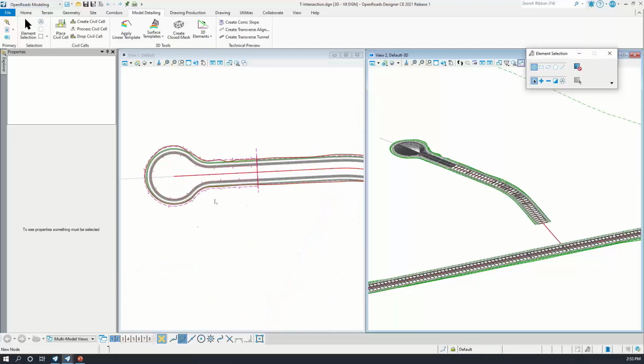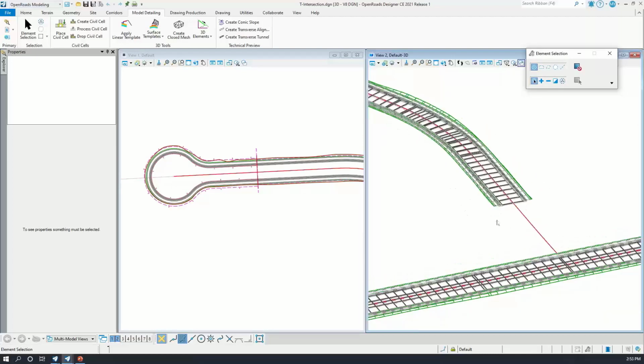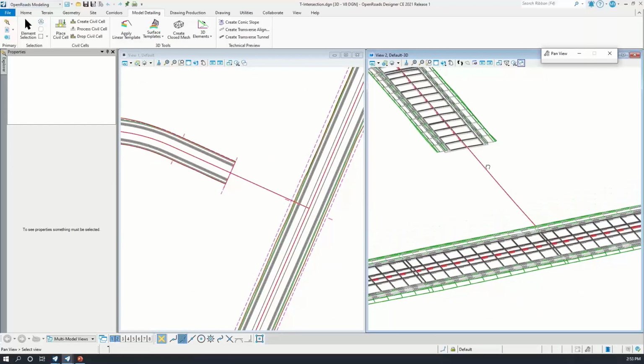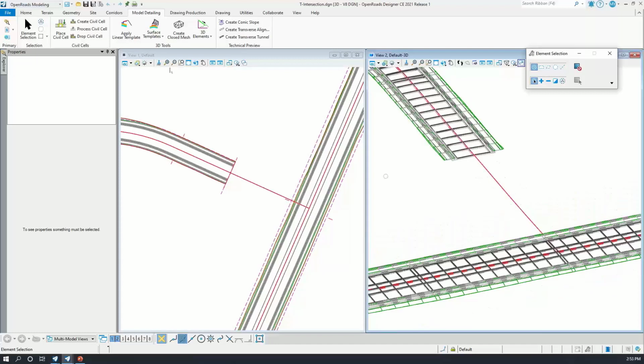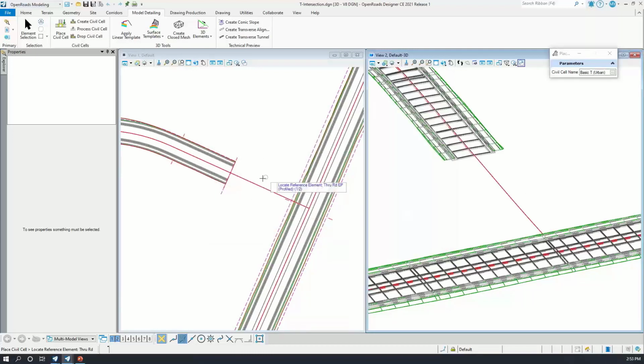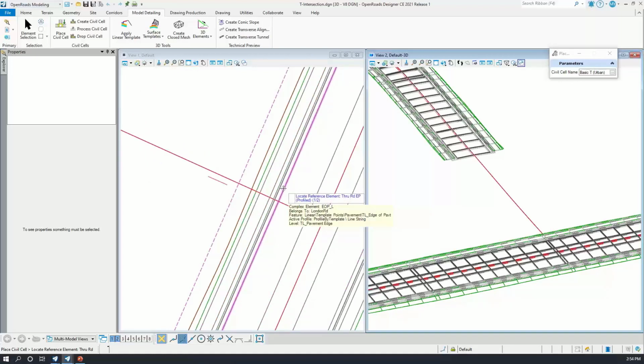Actually, this cul-de-sac here was also placed using Civil Cell, because we also have some Civil Cells available representing the cul-de-sac. I would like to show you how an intersection can be created automatically by utilizing Civil Cell. Again, going through the same process, using the same basic T-urban type, since I have a corridor already placed, you have to make sure you identify the right linear element that your Civil Cell would reference.